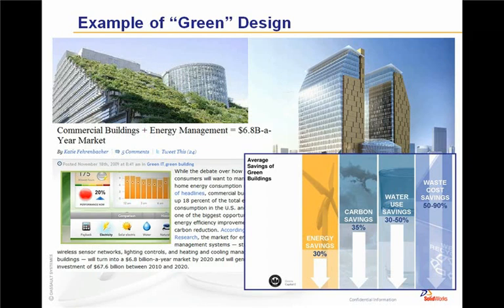So some of the things you would obviously notice in these green buildings are on-site renewable energies, especially solar and geothermal, external solar shading devices, atrium spaces integrated with the climate management system, triple glazing, use of water instead of air for cooling, radiant cooling systems, rain capture and water recycling systems, and efficient lighting systems. So with sustainable design, definitely these building projects are able to save at least 30 to 40% on energy and 20 to 40% or more on water savings as well.